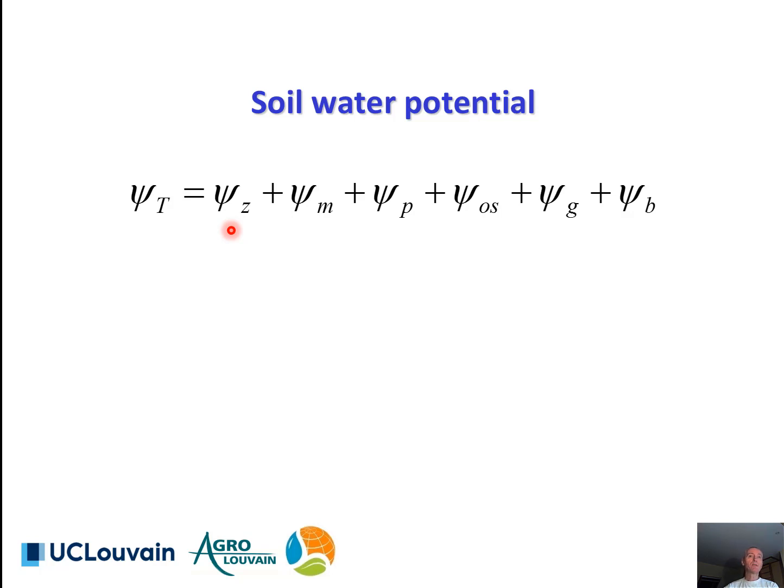Very simply, if a soil water particle is situated at 1 meter depth and the reference water body is at the soil surface, we should introduce an amount of work per unit of weight of water of 1 meter for transporting the water particle towards the soil reference system. This illustrates directly the practical use of the pressure head concept expressed in meters. In all cases, we can define a reference system, and the gravity component of the water potential is just the vertical distance in altitude between the location of the considered water particle and the origin of the reference system.